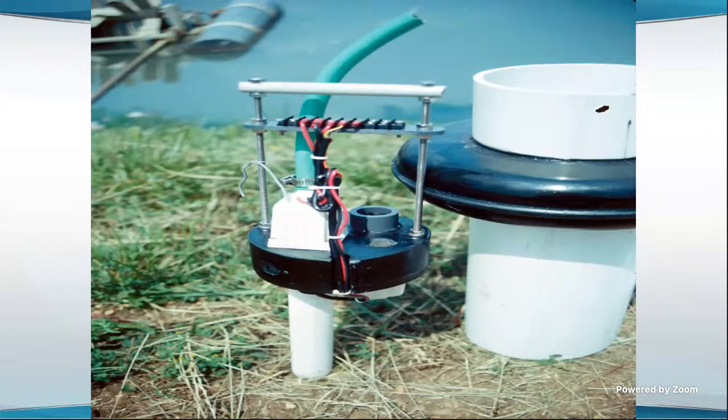Kind of the opposite problem happens in shrimp farming. I think most shrimp farmers, maybe because of the value of the crop, tend to, at least in Asia, use more aeration than they need. And maybe also because in Asia nobody ever monitors oxygen, and they want to make sure they don't have low oxygen in the pond. But whatever the reason, there's been a fairly poor job of matching aeration runtime and aeration capacity in the pond with the biomass, and that wastes energy.